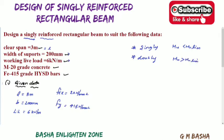After knowing this condition only, we can move to the design, whether it is a singly reinforced beam or doubly reinforced beam. Mu less than Mu limit means we can prefer singly reinforced design, and Mu greater than Mu limit means we can prefer doubly reinforced rectangular beam. But here in the question itself, they directly mention to go for singly reinforced beam. So based on that only you can design this.